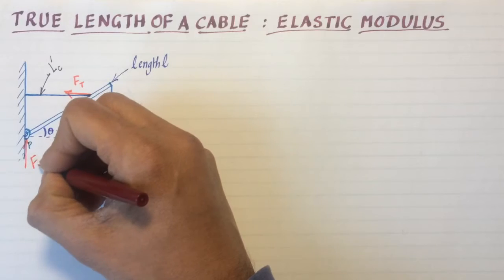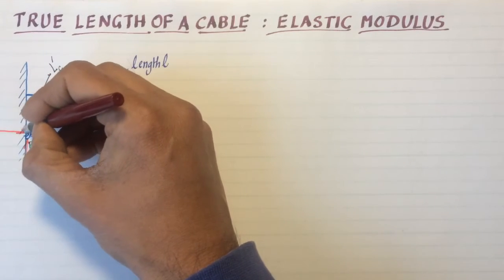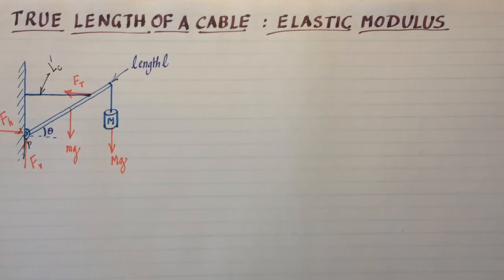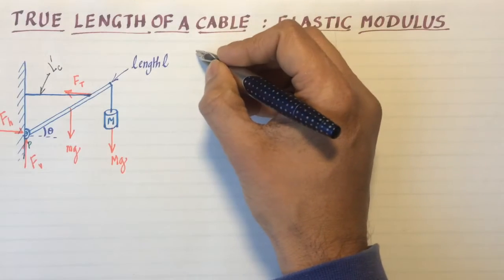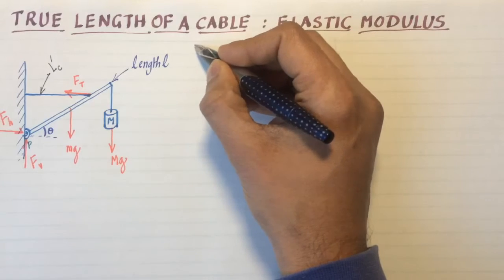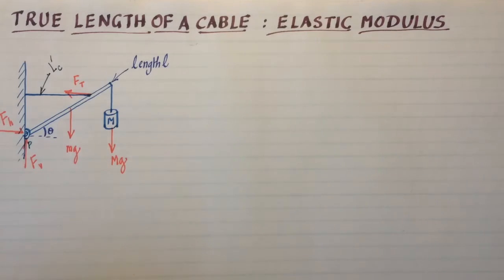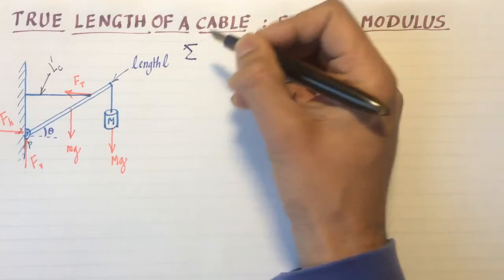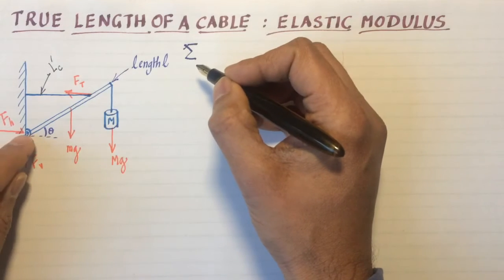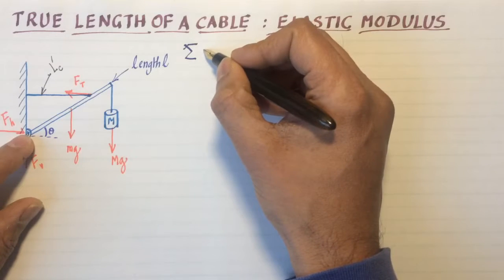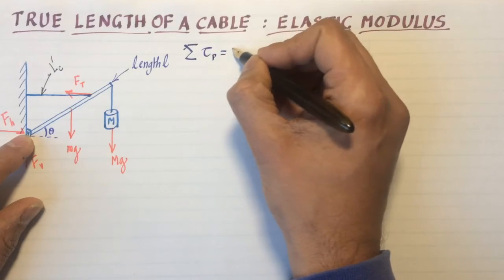There's going to be the vertical force and the horizontal force on the hinge. I'm not too concerned with those forces. Let's write the conditions for equilibrium, which is basically Newton's law for rotation and translation. So Newton's law for rotation gives us, about the pivot. Remember, the pivot is the point about which we take the torques, because two unknown forces, namely F sub h and F sub v, pass through it. So the sum of all the torques about the pivot equals 0.